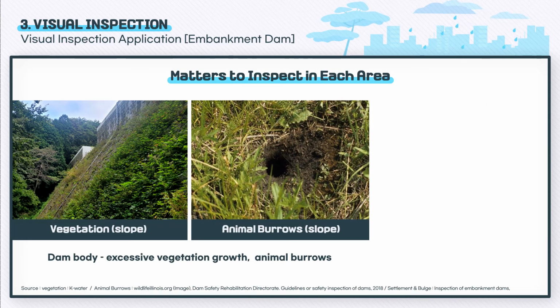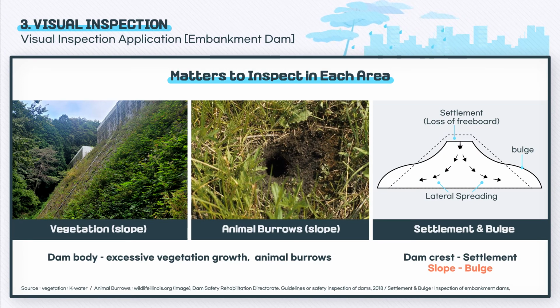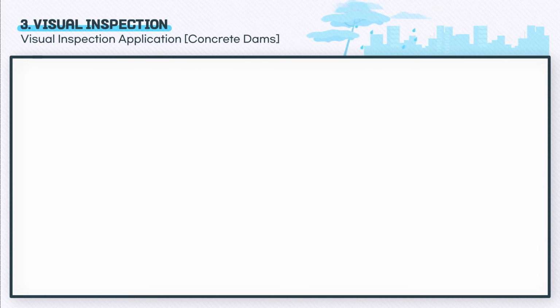Furthermore, it must also be determined whether any excess vegetation growth or animal burrows are present in the dam body, and whether settlements are occurring on the dam crest or bulges in the slope. Let's take a look at concrete dam inspections.